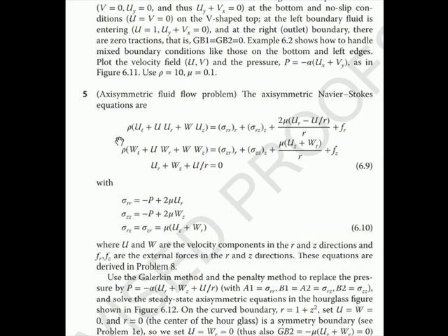We also derive the axisymmetric fluid flow equations, and again, it's a huge mess, but that means that your region has to be such that nothing depends on theta. You can switch to cylindrical coordinates r, z and theta, and there's no theta dependence if everything's symmetric around the axis, in which case you can reduce the fluid flow problem to a 2-dimensional problem, and it looks like this. Again, it's not at all obvious where some of these terms come from. It's rather complicated, but there they are. There's the axisymmetric Navier-Stokes equations. This is the axisymmetric divergence equation.